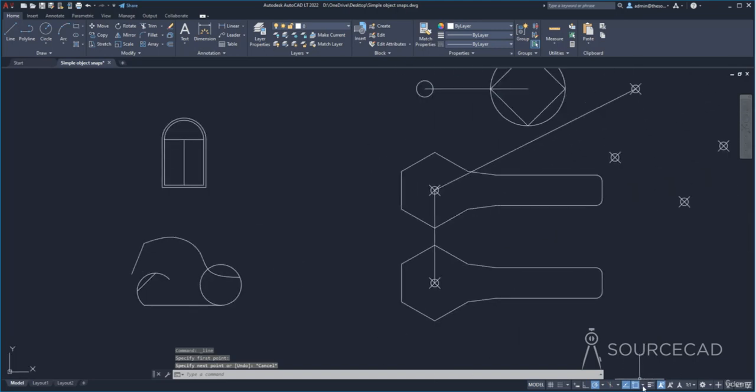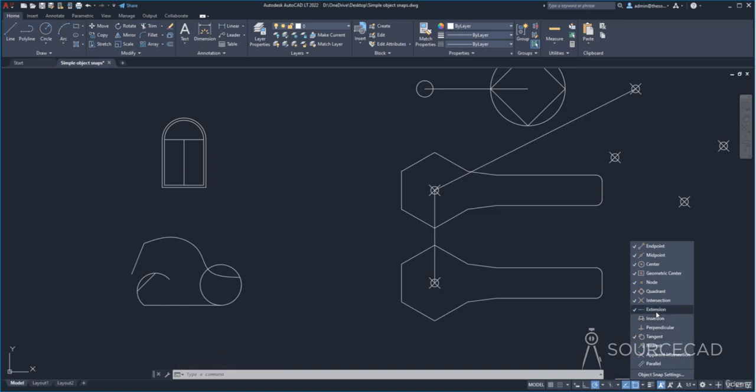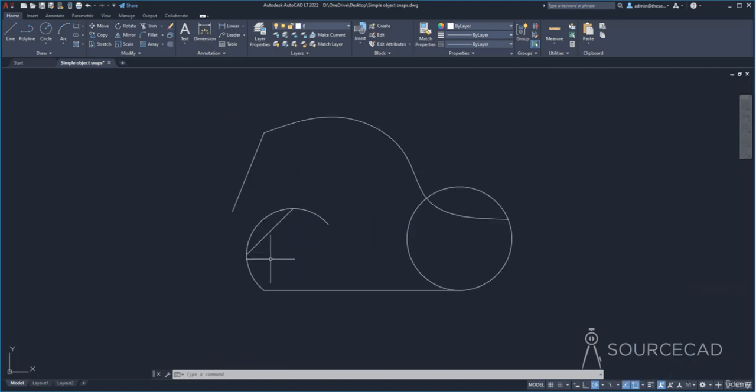All right, let's see what we have next. The next is extension. For extension, we'll use this arc as an example and this line. So I'm going to zoom into this area. Let's activate extension first. Okay, it is activated, so I'll just go back to this. Now for this, you don't need any command. Extension will simply extend your existing geometry. For example, if you want to extend this line exactly along its direction, then click this last grip. By the way, these blue dots are called multifunction grips. Click and just extend it in this direction.